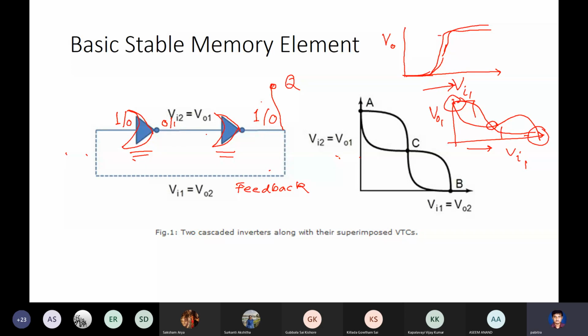Okay. And one of the inputs is as before, this feedback loop. The other input we'll call the external input. Let's call these a set input and a reset input. So I replace the NOT gate by a 2-input NOR gate. One of the inputs stays this feedback connection. And the other input, of one NOR gate we call the set input, and of the other NOR gate we call the reset input.